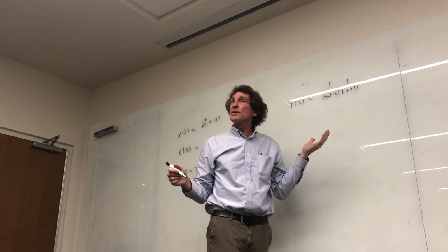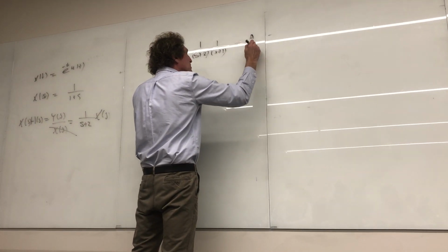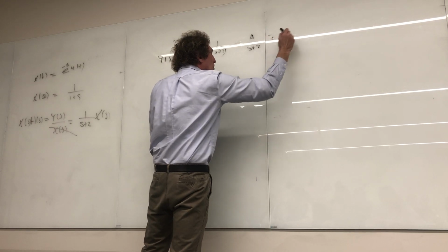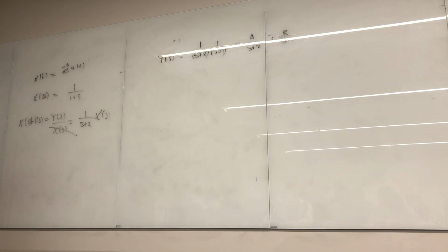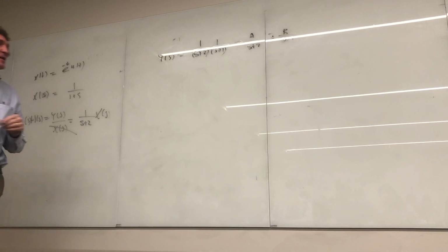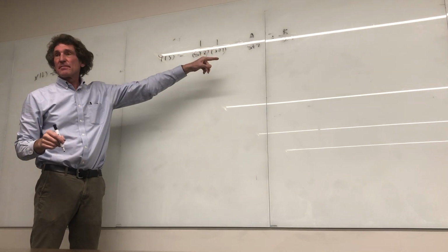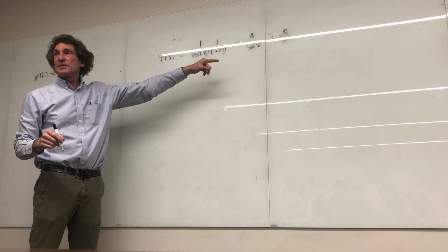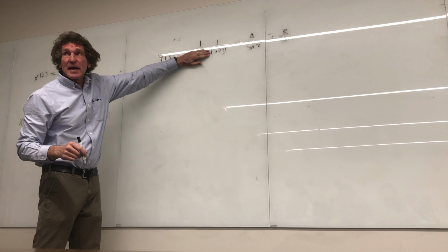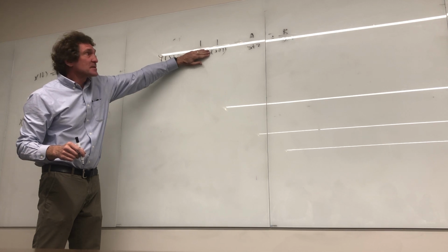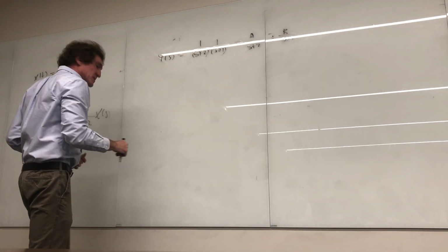All right, well, how do we solve this? We want to go back to time. What do we do? Partial fractions. Let's just do it together. We have a over s plus 2 plus b over s plus 1. Those are the poles. Do you all agree? All right, how do I get the first value of a? What do I do, people? Where's the pole for a, for instance, in the denominator? s equals minus 2, correct? So I cover this up, and I evaluate the remainder at s equals minus 2, correct? What is that? 1 over minus 2 plus 1 is minus 1. Do you agree? So that just means this one's minus 1.